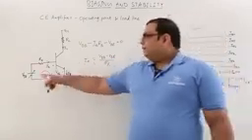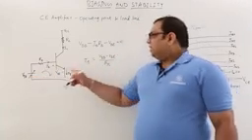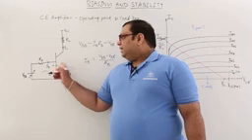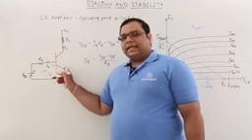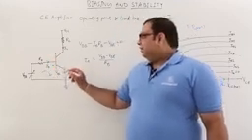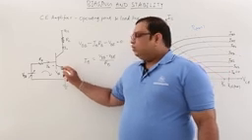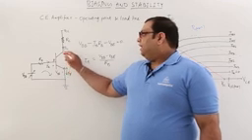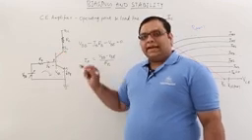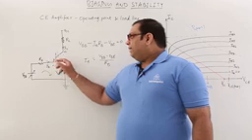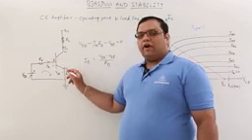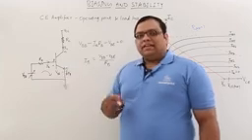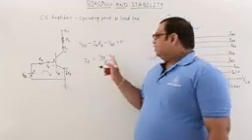VBB is the supply voltage we are applying, and VBE is a constant voltage. Observe the transistor symbol carefully, with the arrow direction. This is a P type semiconductor and the others are N type, so this is an NPN transistor. We have to forward bias the P to N junction, and when you forward bias a PN junction diode, the voltage across it will always be 0.7.